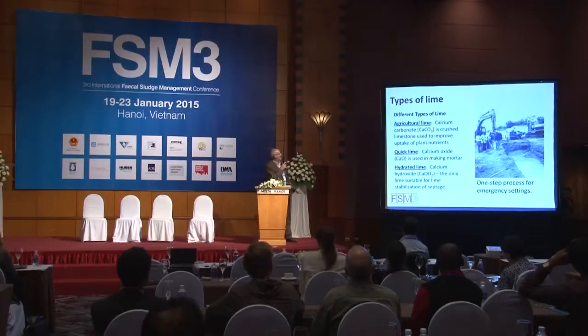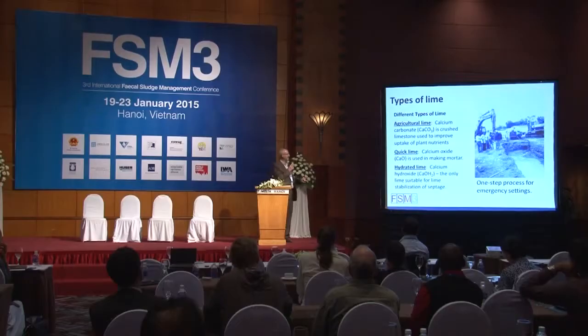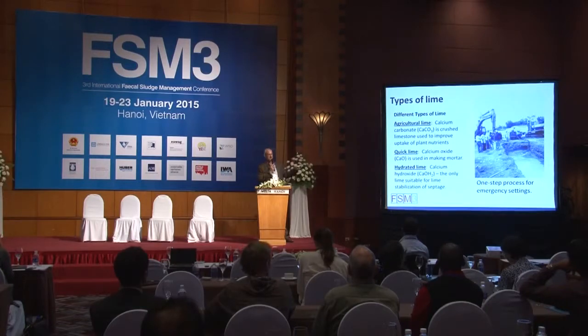So this is something about the different kinds of lime, and it's important to note that when we're talking about lime stabilization, at least for our purposes, we're using hydrated lime, which is calcium hydroxide. The process doesn't work that well if you're just using agricultural lime, which is a little bit different. And the image is a one-step lime stabilization process where the reaction occurs right in a trench.